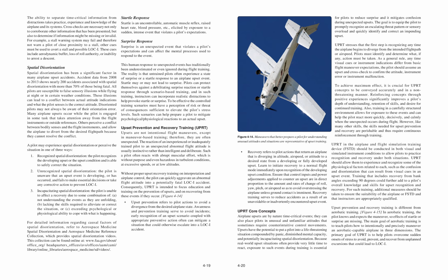UPRT core concepts. Airplane upsets are by nature time-critical events. They can also place pilots in unusual and unfamiliar attitudes that sometimes require counterintuitive control movements. Upsets have the potential to put a pilot into a life-threatening situation compounded by panic, diminished mental capacity, and potentially incapacitating spatial disorientation. Because real-world upset situations often provide very little time to react, exposure to such events during training is essential. 4-20.